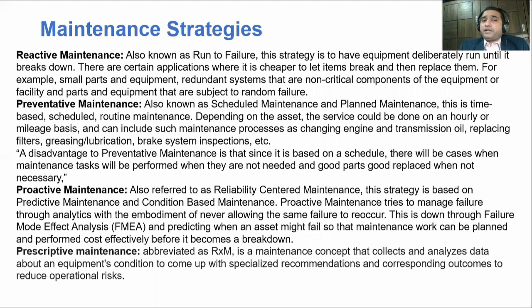Okay, then comes the preventive maintenance. So preventive maintenance is generally done for the very critical equipment. And again, it is a time based scheduled routine maintenance. Like you decide that for these machines, because of this reason, we do the monthly maintenance. For this machine, because of this reason, we'll do the weekly maintenance. For this machine we'll need to do these activities daily, like oiling or something. Okay, so that is what you plan for in the preventive maintenance.